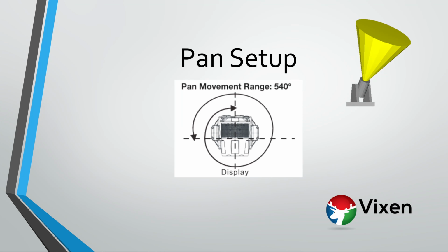Most moving heads pan from their starting position in only one direction. This effect needs to pan some moving heads to the left and some to the right. To prepare for this, the effect initially pans all the moving heads 360 degrees. When you add the effect to the timeline, Vixen looks at the total range of pan movement and calculates a pan start value to pan the fixture 360 degrees.